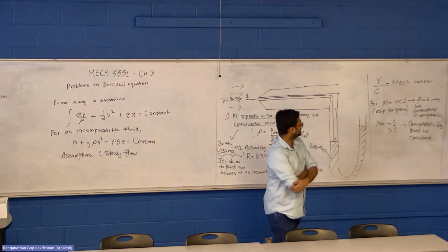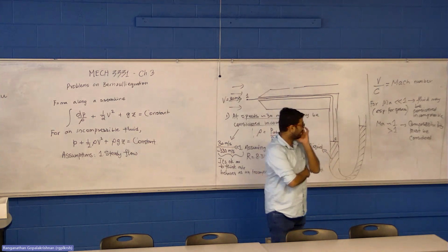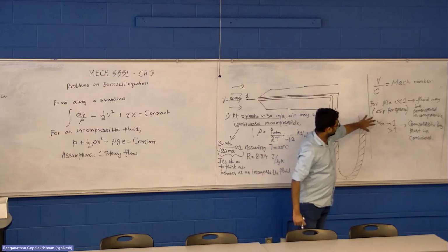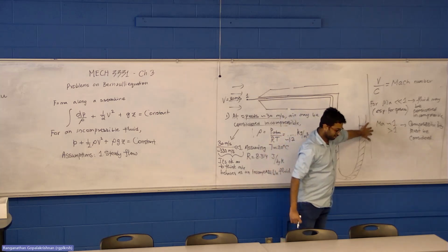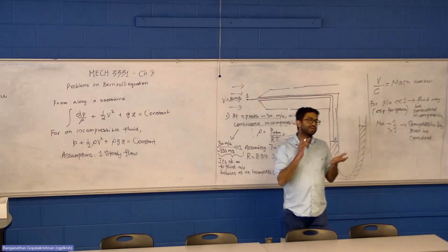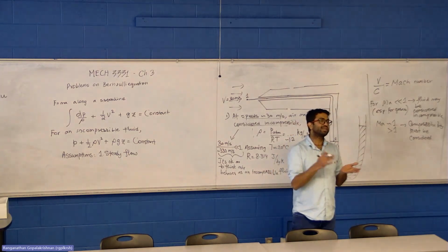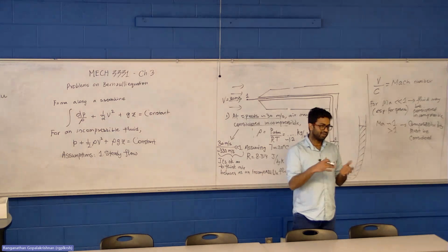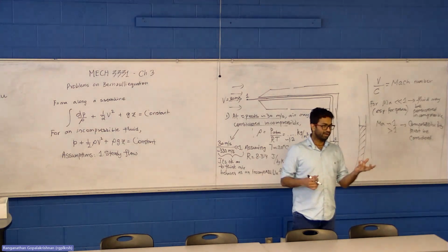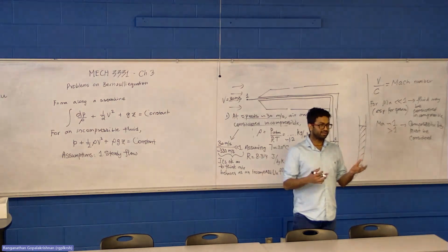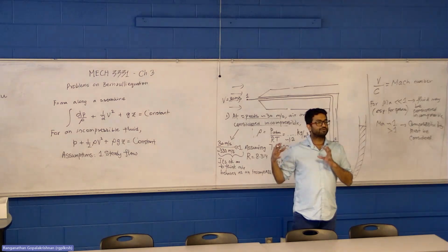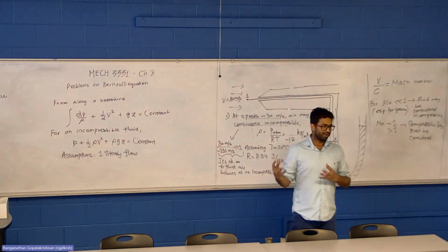The other reason is that for gases, this is strictly true. For liquids, as they move at higher speeds, more effects like viscous heating come into play. So a liquid will not remain a liquid at those conditions. It will start vaporizing and you will get a mixture of steam and water or superheated water.